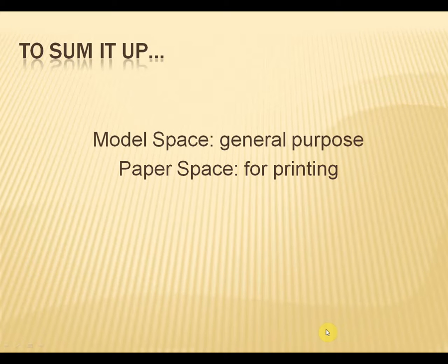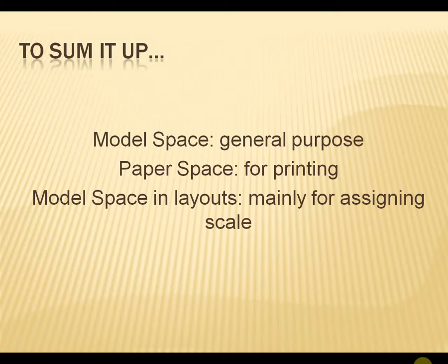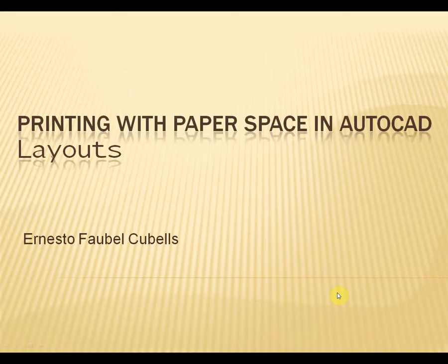So to sum up this video, you have a model space with a general purpose, mainly for drawing, modifying, measuring, working in general, and when you want to print you have the paper space as a very powerful tool. But apart from that you have a mixed way of working. The model space in layouts is mainly important for assigning the scale to each viewport in the layout. And that's all.